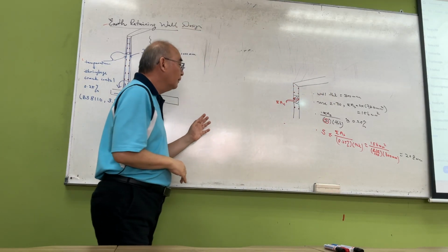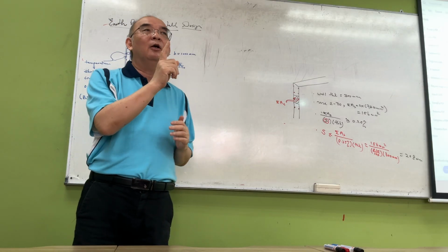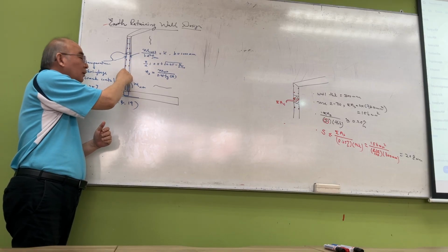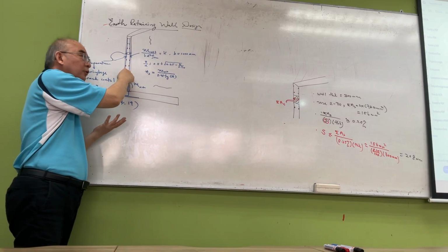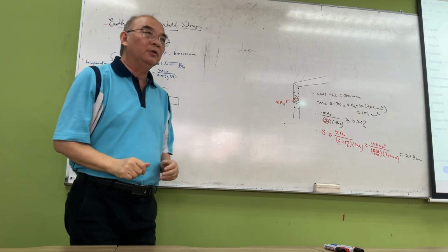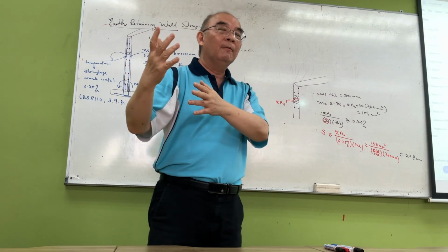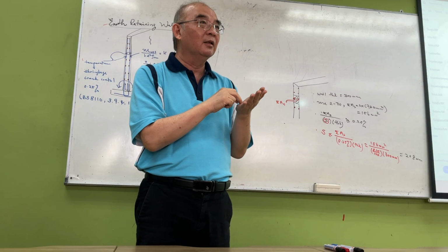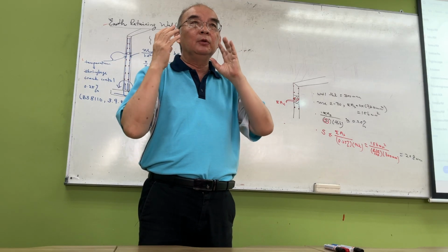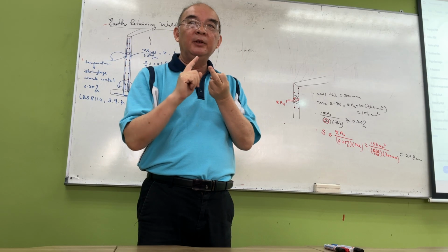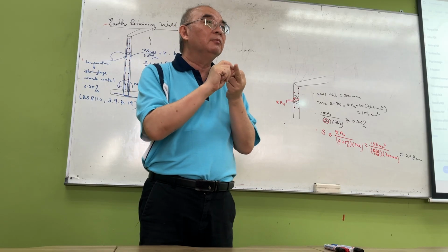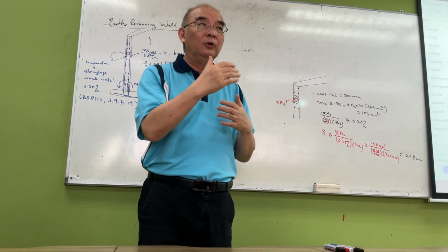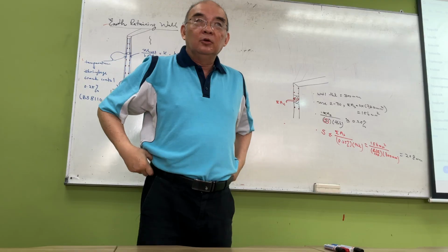So an experienced engineer like me, in order to gain time, we have to do it in parallel. That means I know the wall. I just tell the drafter, okay, this one you take T20 at 200. This one you take, let's say, T8 at 200. The horizontal you take T10 at 200. You go and draw. Okay. Then at the same time I design. I check my design. So if you are experienced enough, your initial estimation is close to your design results.